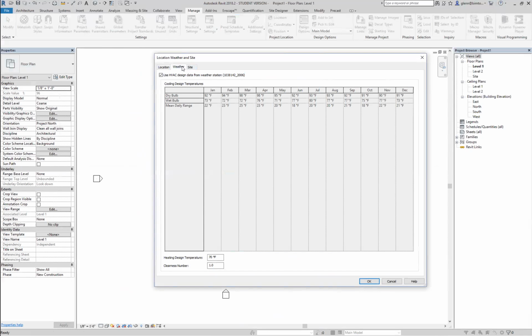We might want to think about this. Some interesting things will happen here. It's warm. Our building will have to worry about cooling quite a bit. So we'll have to think about shading and how the sun's hitting the building. Having walls and walls of glass with no shading probably wouldn't be a very good thing. We could also think about the widths in our building, if we wanted to have any sort of natural ventilation. It may be so hot that it's impossible to think about that, but we can try to incorporate that into the design too.